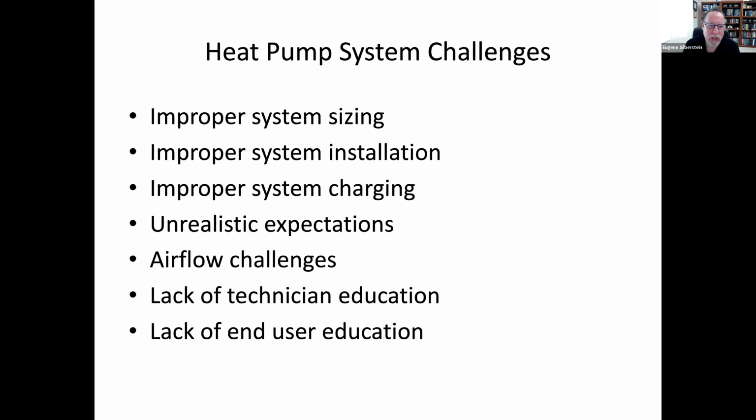Like Thomasina was mentioning before, talking about gas systems. Well, if you're operating a gas-fired furnace, your discharge temperatures are going to be a lot higher than they are with a heat pump. So when you have an end user who is used to fossil fuel heating systems and they feel the discharge air and it's not as hot, then the heat pump in their mind is not working correctly. There are a lot of airflow challenges, especially when we get into inverter controlled systems.